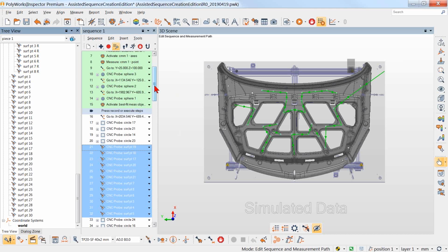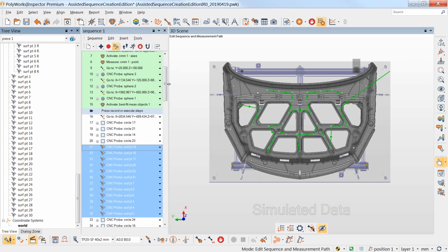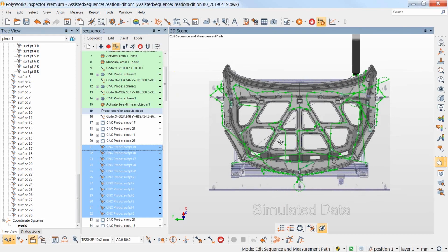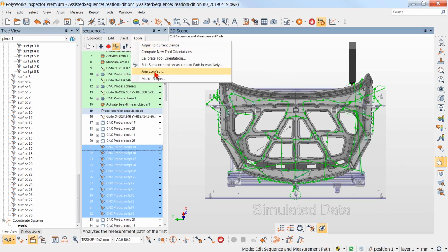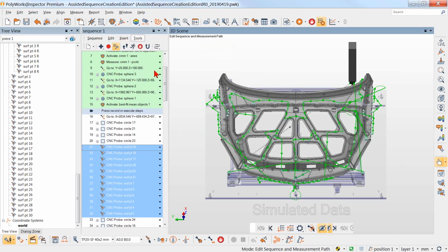Now, one last thing before I go: I've talked about analyzing the toolpaths when we've had a collision. But one of the things that I think a lot of people don't take into consideration is that we can actually analyze the toolpath of the entire part. So if I were to turn all of the paths on to see what's happening through here, I can actually come through and go to Analyze Toolpath the third way, which is through the menu, say Analyze Toolpath.